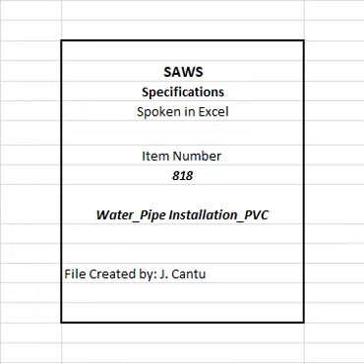4. The measurement of each line of pipe of each size will be continuous and shall include the full laying lengths of all fittings and valves installed between the ends of such line, except that the laying length of reducers will be divided equally between the connected pipe sizes. 5. Lines leading to a tapping connection with an existing main will be measured to the center of the main tapped.